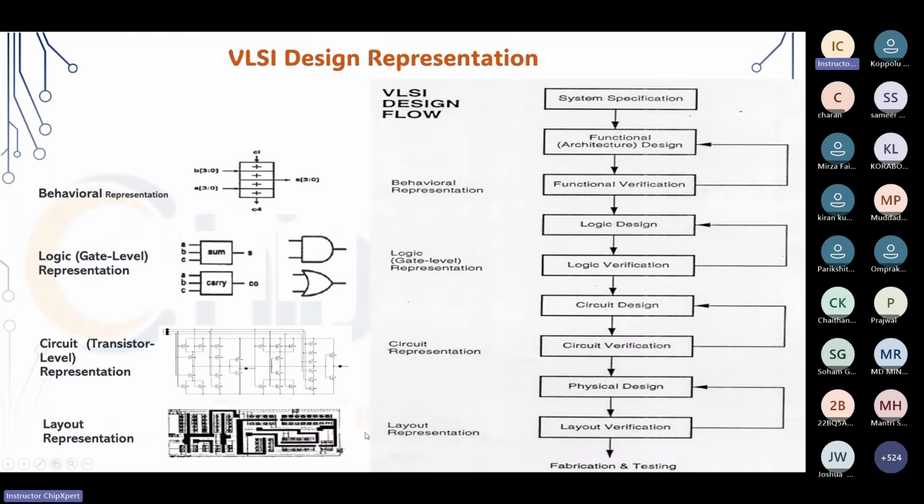This will be put together by the physical design people, physically verified by the physical verification people, and tested properly for frequency, how the speed is working. They will then be given to the fabrication people by the end of the design cycle. That file format is called a GDS file. It goes from RTL to GDS.